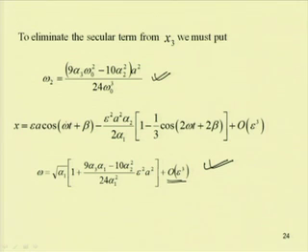So, this frequency relation shows the dependence of the amplitude response on the frequency. That means the amplitude response of the system influences the frequency of the system in the case of a nonlinear system, but in the case of a linear system the frequency is independent of the amplitude of the excitation.